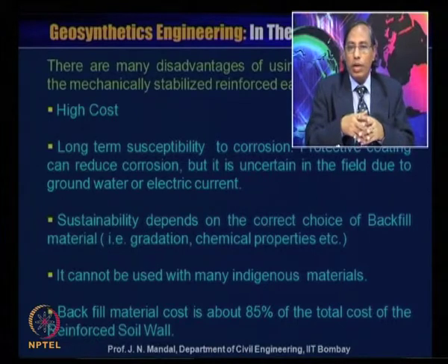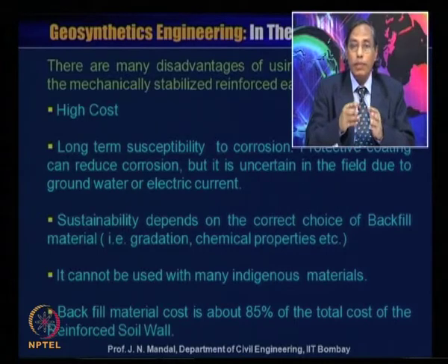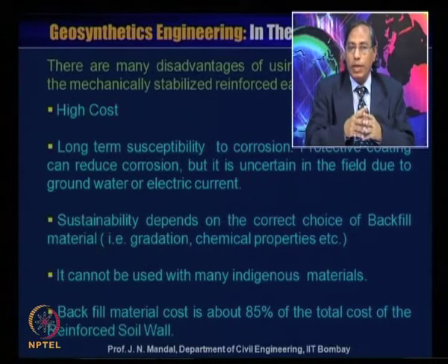Sustainability depends on the correct choice of the backfill material, gradation, and chemical property. This is very important, that what kind of material you choose should meet certain criteria as per the specification. It cannot be used with many indigenous materials, and backfill material cost is about 85% of the total cost of the reinforced soil wall. Generally in India, it may be about 25 to 30% of the total cost of the reinforced soil wall.